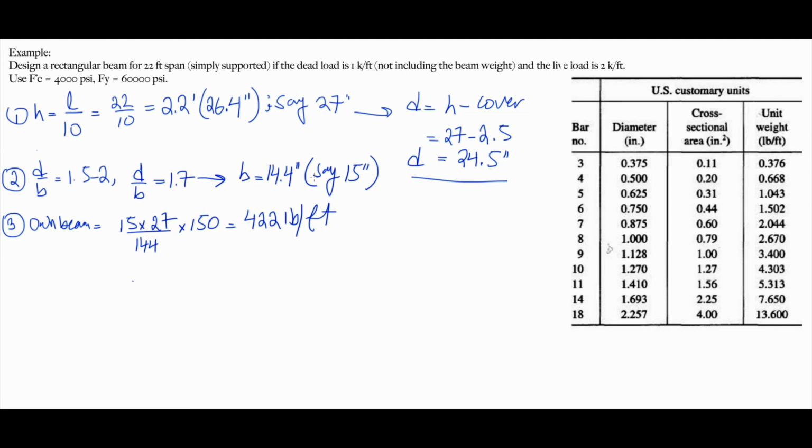Great. Okay, since it is simply supported, I have the loads, right? But I have to factorize the load. Recall from the structural analysis course, the ultimate load is 1.2 times dead load plus 1.6 times live load. And this will give me a final load of 4.87.